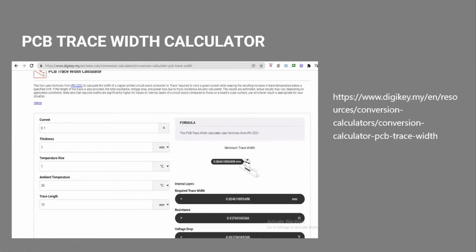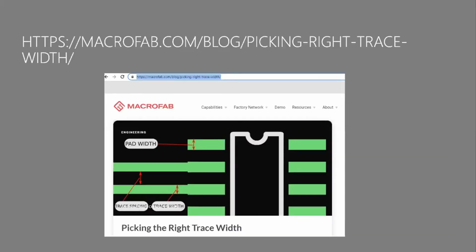Right now we are assuming that you're running at 100 milliamps, 200 milliamperes, so that's very low current. You're not running at 1 amp or 2 amps, so we are less concerned about a bigger width. A small width will be good enough, 0.1 or 0.5 millimeter. You can look into this website for further information on the pad width and the trace width. These are more detailed design matters. My objective today is to get you started very fast, or at least guide you a little bit to kickstart your project, from a messy wiring into a more organized PCB.